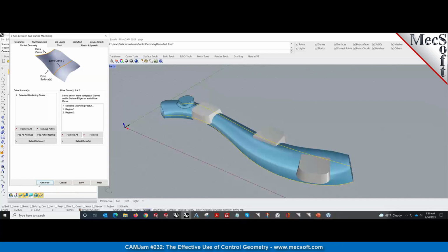But in 5-axis mode, apart from the X, Y, Z coordinates that we obtain from slicing, we also have the surface normals we use to position the tool along that surface normal. And then obviously there are some additional controls you can use to control the angles and the axes of the tool. But to define that, you have to have a surface. The surface basically gives us not only the X, Y, Z points to position the tool to, but also the tool axis vectors to use to position the tool.